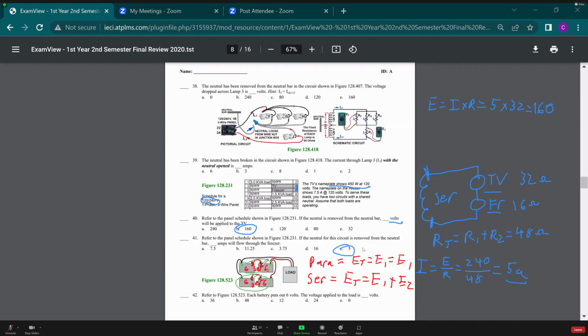So I have series, and then parallel connected to the two. What we're going to do is add the voltages that are in series, and then they stay the same in parallel. So if I have 6 and 6, that's 12 volts for my top set, 6 and 6, 12 volts for my bottom. Those two voltages will be the same going to the load, so I am applying 12 volts.